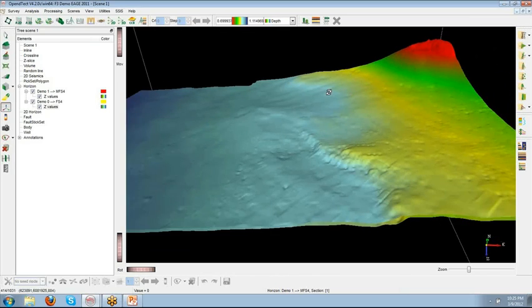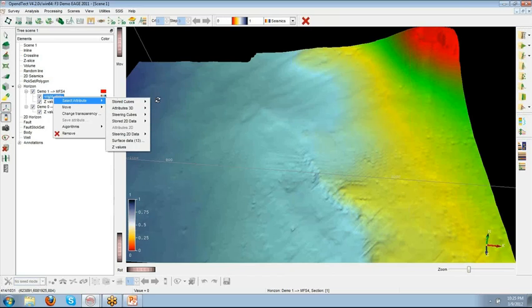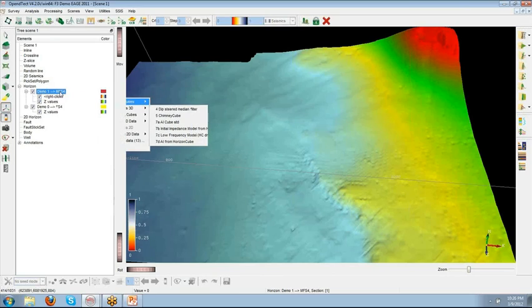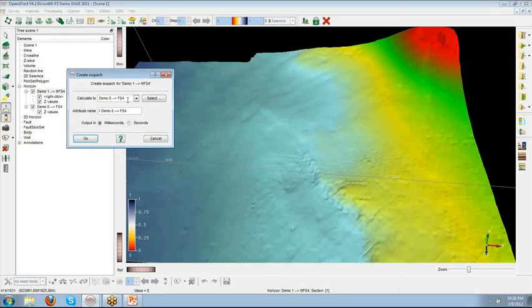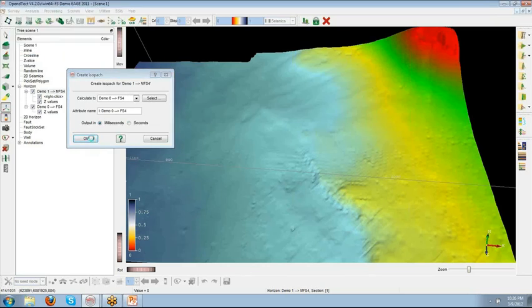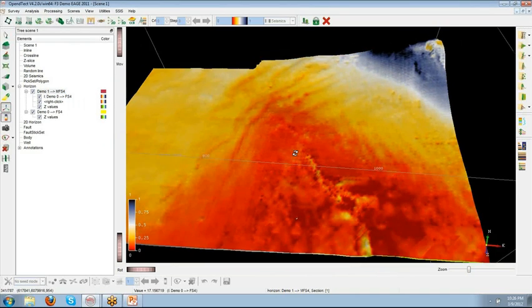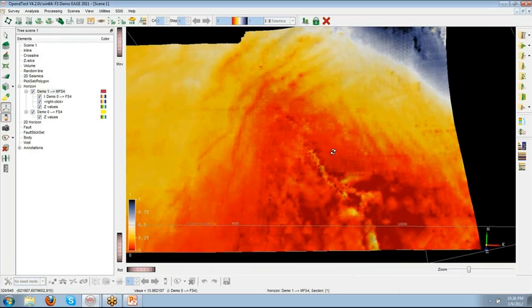They represent a rather small interval, and in order to assess the time difference, the very first thing I'll do, and that is part of the interpretation, is that I'll compute the isopach between the top and the base horizon, and the output will be displayed as a grid on the top horizon, which is this one. So we see on this isopach map the time difference between the two horizons that is roughly around here to 14, 20, up to 40 milliseconds.